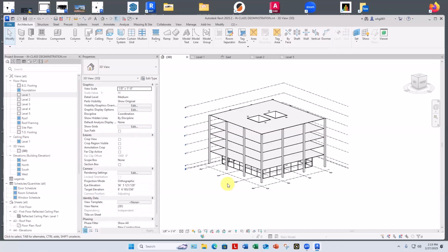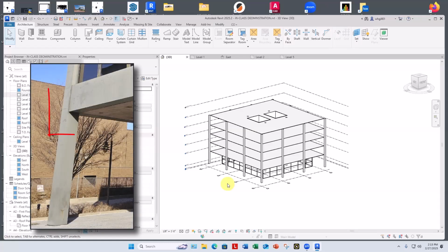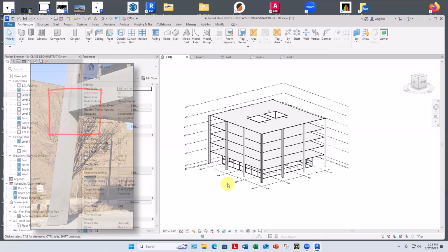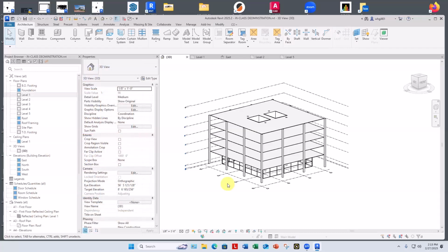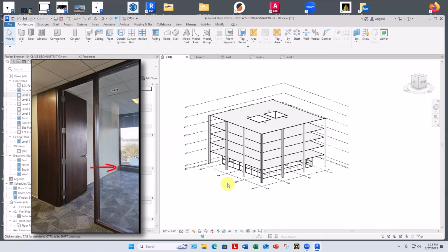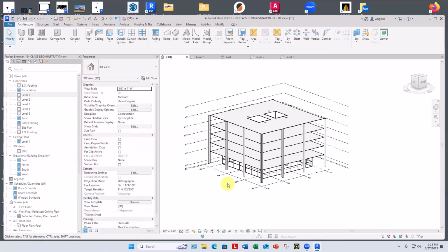I want to explain what's going on with these outside walls. We've got our 15 feet 8 up to the ceiling, and the wall starts right level with them, the bottom of this metal panel wall, and it goes up 4'6" and then comes down 6 inches to the floor. There's just that little lip of a heater air strip. So when we start putting this wall in, we'll be on the level 2 floor, but we're going to have to start the wall 4 feet down from there. It starts at the bottom of the ceiling when we put it in, and then goes up 4'6" and then continues on up. So we'll just see how this flies.